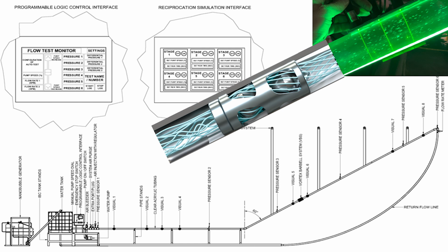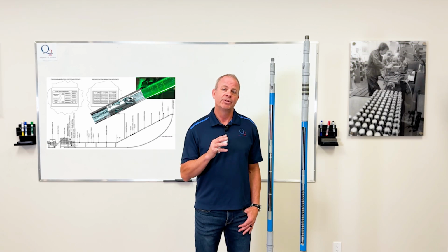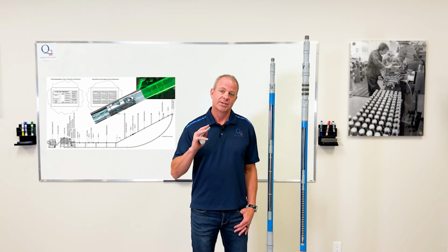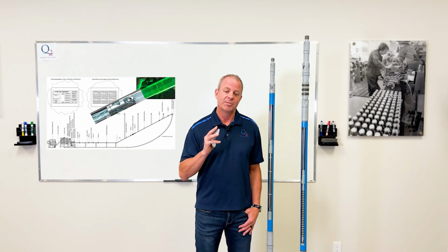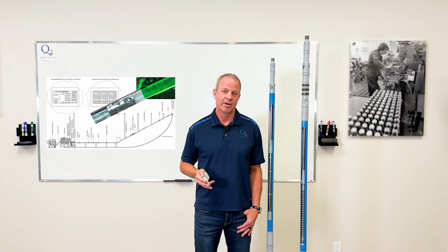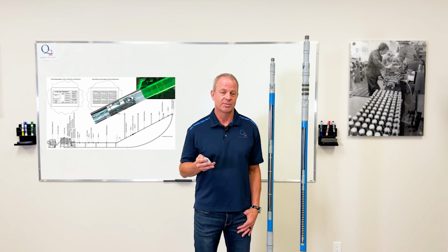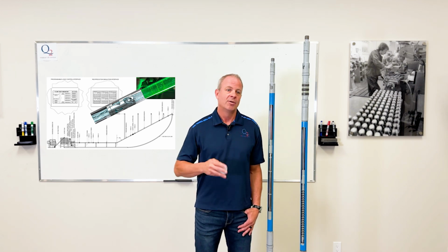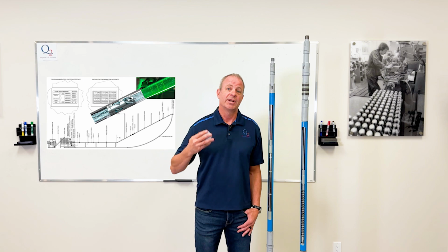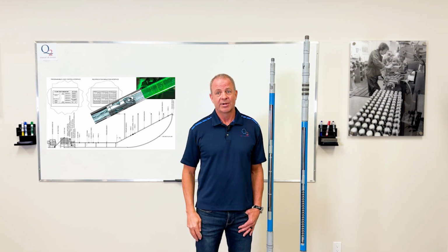Yeah, so in this case we have acrylic tubing, we've got pressure sensors connected to a PLC, and the really interesting thing about that is we were able to measure the differential pressures with respect to different flow rates, and we're able to simulate reciprocation in the well. So that's really important for us, because we're non-steady state. We're always pumping, and you're accelerating the fluid and decelerating the fluid.